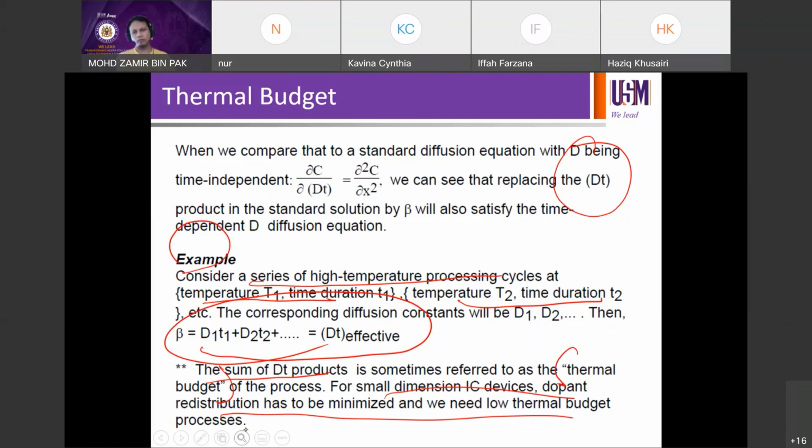Okay, so your dopant profile may start off as something like this. If you plot dopant concentration against X after the diffusion, and run ECV to characterize, you may get something like this. But when you impose another process that is not intended to change the dopant profile, but somehow will change it, it will probably be something like this. Your new dopant profile will probably be something like that, or probably something like that.